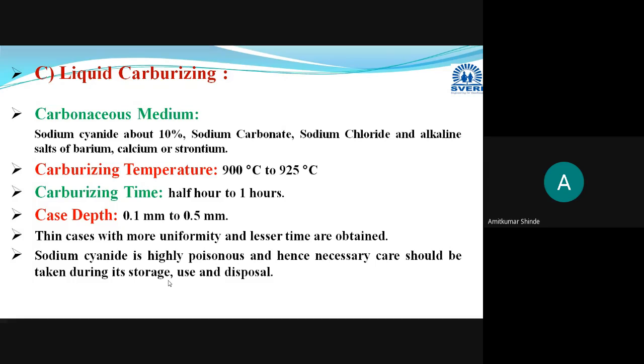Proper care should be taken here, as you are using sodium cyanide in this process. It is highly poisonous in nature, so it is very necessary to take proper care for its storage, use, and disposal. So this is the liquid carburizing process.